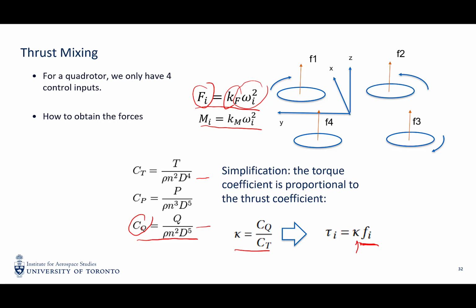So now this gives us a simplified way to obtain the forces on four rotating propellers if we want to have a desired force and torque on the entire body. For controller purposes, we always want the four propellers to generate a desired torque and lift on the quadrotor.